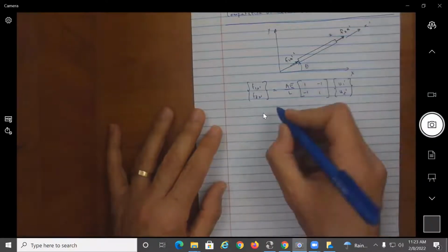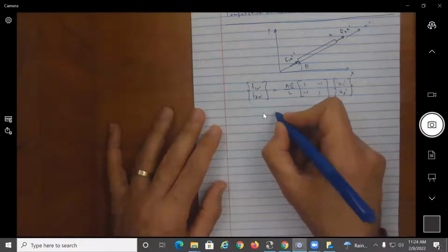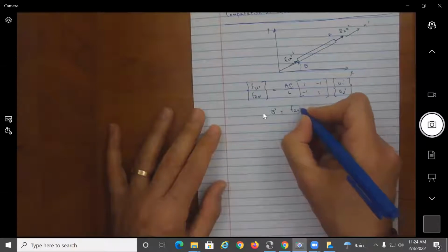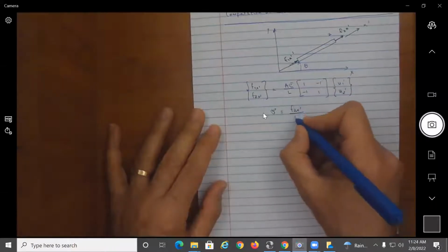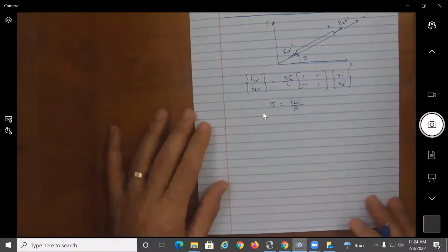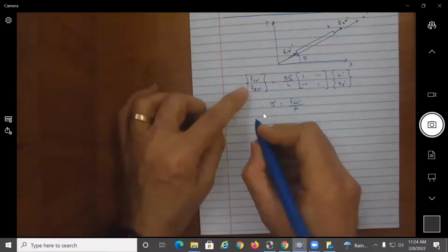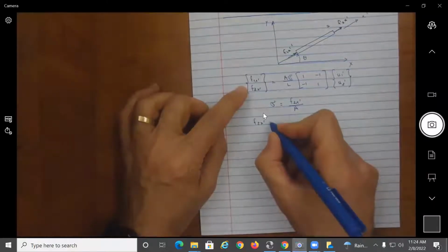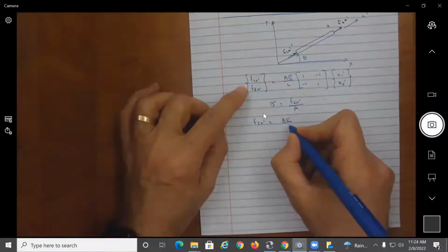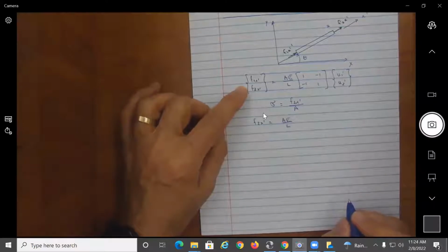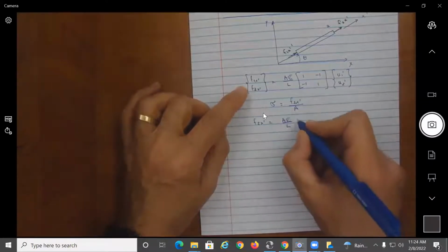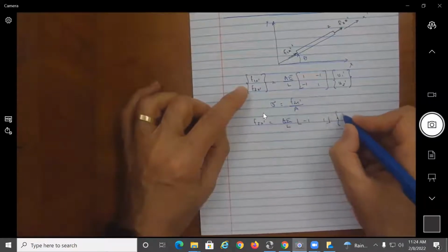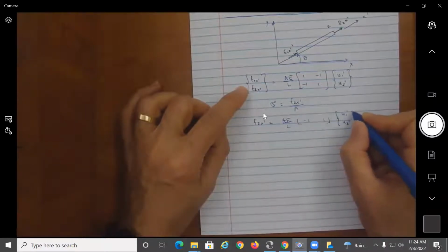So the axial stress in the bar element, sigma, may be expressed as F2x prime divided by the area. If I write an equation for F2x prime, I can write it as equal to AE over L times minus 1 and 1 multiplied by U1 prime and U2 prime.